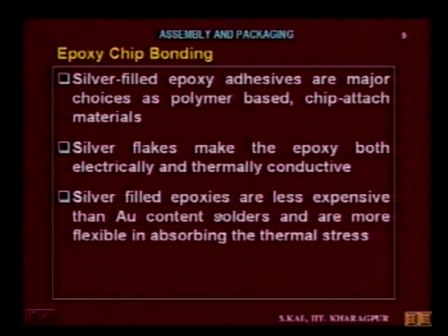Silver filled epoxies are less expensive than gold content solders, such as the gold tin solders which were used earlier, and silver filled epoxies are more flexible in absorbing the thermal stress. This is a very important criterion.